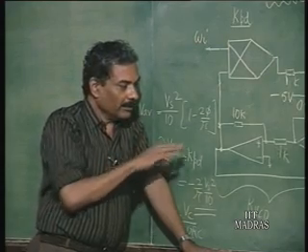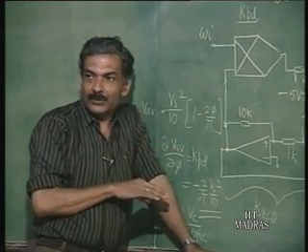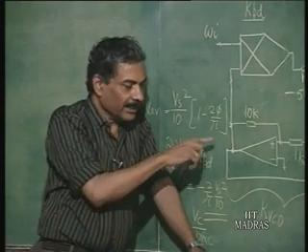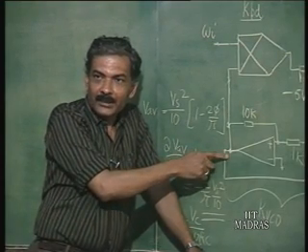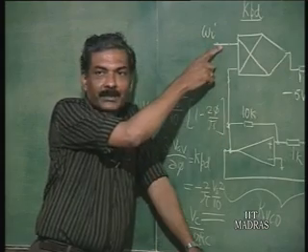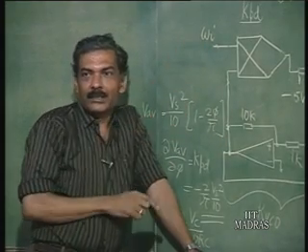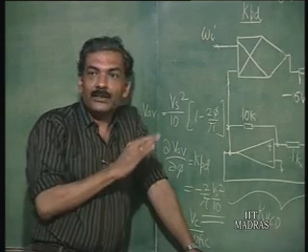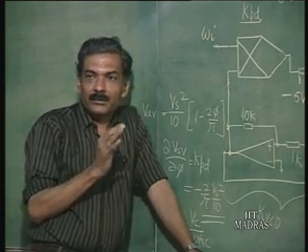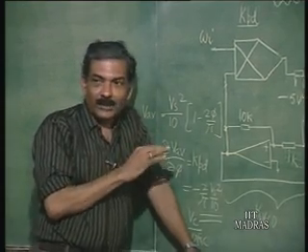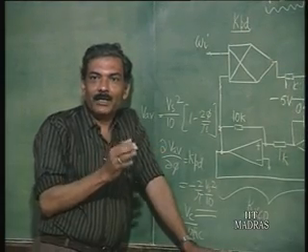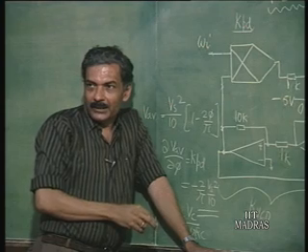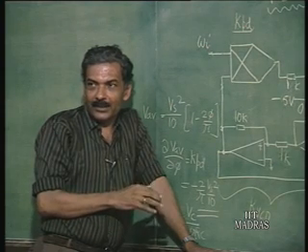In the oscilloscope, when you see this waveform, only one waveform triggers the oscilloscope, and therefore we have made it such that it gets triggered by the free running frequency. So the input frequency waveform, which is seen on the other vertical deflection plate, is going to be not stable. The moment it gets locked, you will get a stable waveform, both for the input as well as the output. So, this is the way to recognize that it has got locked.